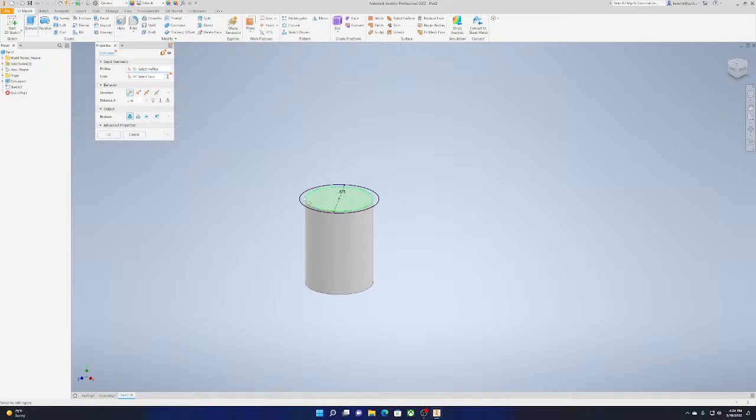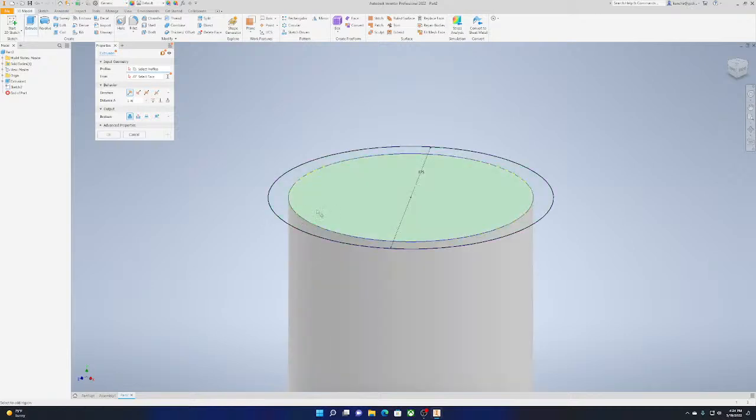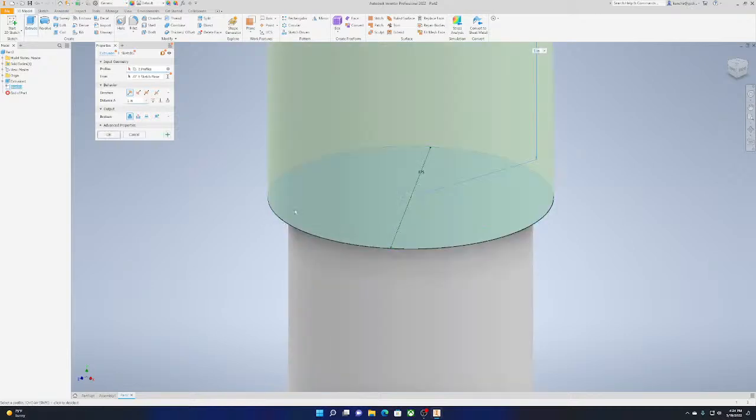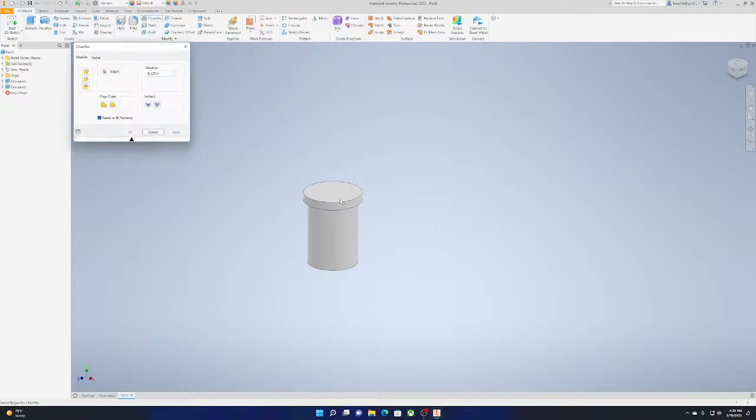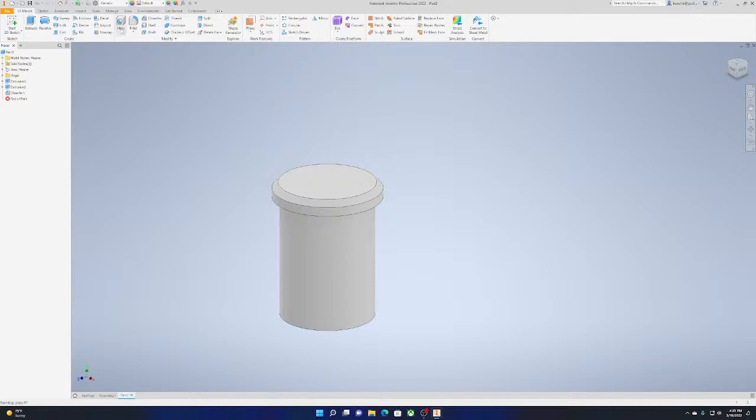And then I'm going to extrude this one out. What's really interesting is when you do it, it'll ask you if you want to do the whole thing, but you can just pull that. And then I'll do a height like that. And I'll chamfer it. So we can do that. And that's too big of a chamfer. So we'll do 0.05. That looks cool. Can we fillet this edge? And you can. So I'll also do a really low fillet.